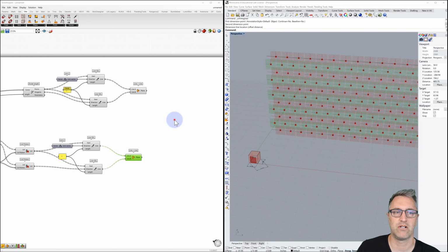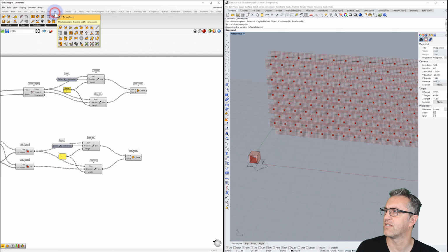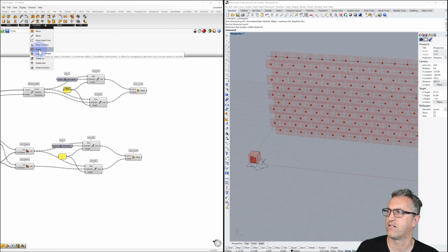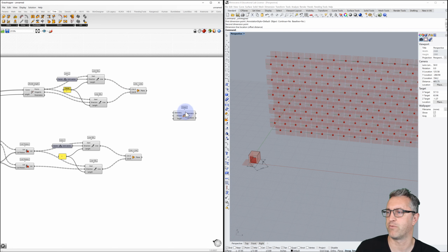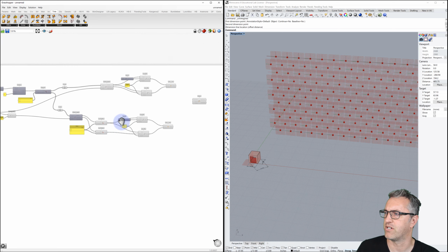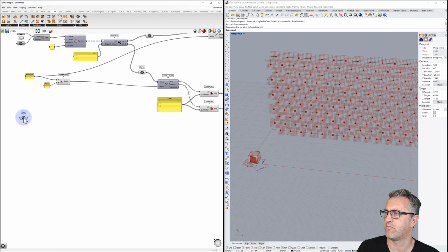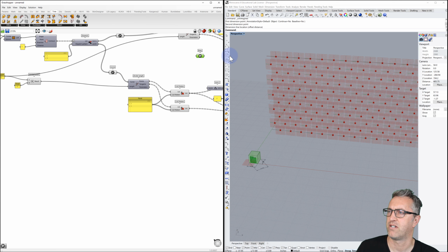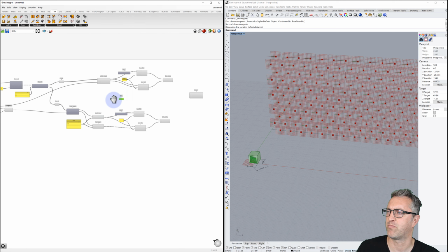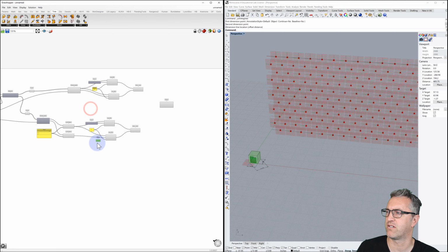And so we're going to do this with the orient tool. And this is under translations, Euclidean, and then orient. And so what do we need when we orient a box, or when we orient an object? First, we need the geometry. So our geometry is going to come from our B-rep. I'm going to break my rule a little bit.